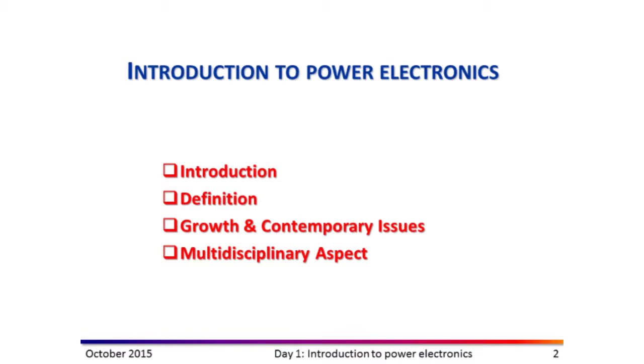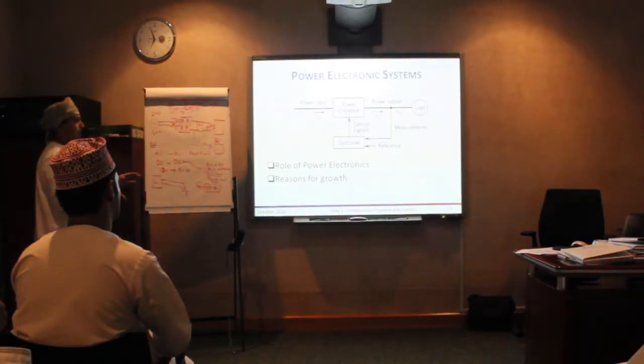Now you have the input, which is 240 volts, and you would like to get it like 20 volts here. But suppose that this load is changing and you want to keep this one constant, so you need a feedback loop, right? What this loop is doing exactly, for example in this case, is sending the voltage and comparing it with the reference, and there are different types of controller that can be applied. The controller will try to create a signal that changes or controls those circuits in order to get that 20. And this one is important.